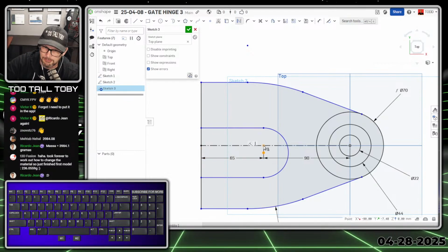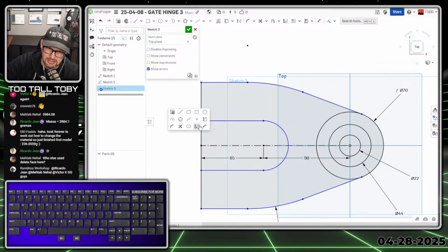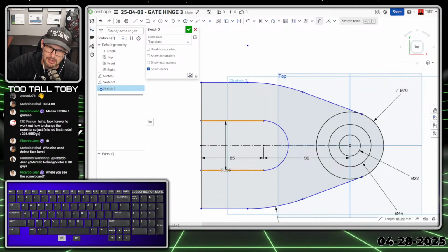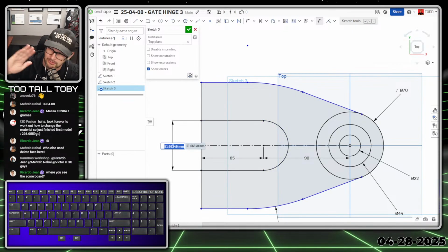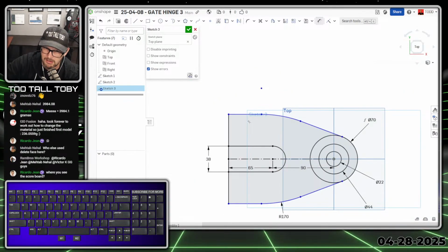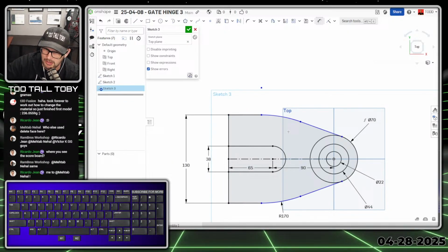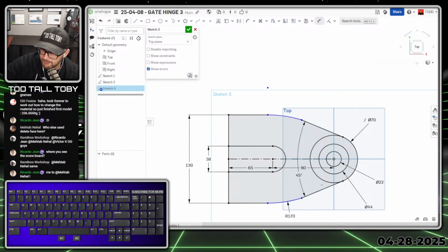Now this point and this point, I'm going to press I. That way those 2 points become coincident. And then I'm going to press the S key here and just add a dimension from here to here. Now, we also could have done that with a slot. Slot would have been totally reasonable there as well. But I'm just going to do it here with more traditional sketch geometry. Continuing with my dimension command, since I'm already in there, I'll make this 130. And then I'll add in an angle here of 45 degrees.